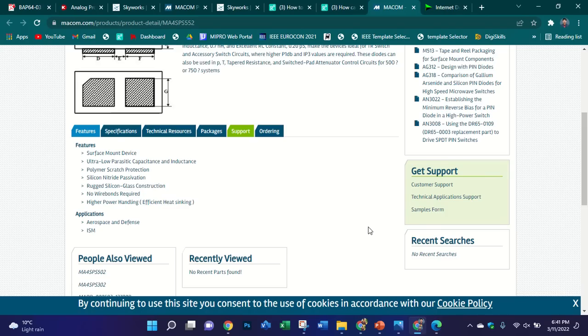But when I solder the pin diode across the fabrication, the result has some frequency variation, or the return loss changes. So if your diode is working, then your frequency will shift. Maybe not exactly as in the simulation, but less than minus 10 dB at any frequency. It means your diode is working, with no problem with the diode.